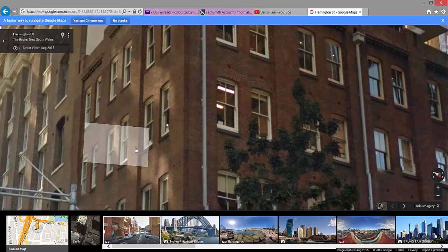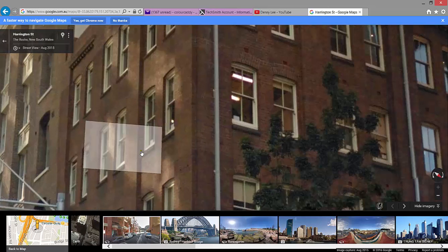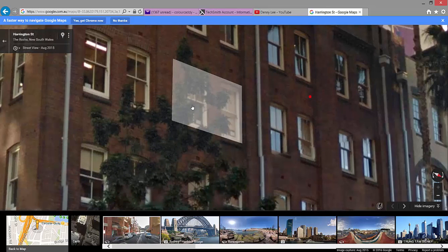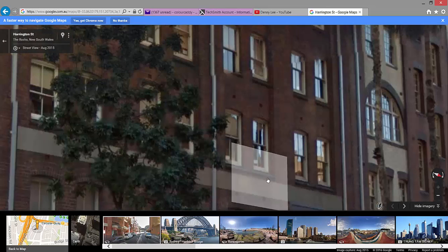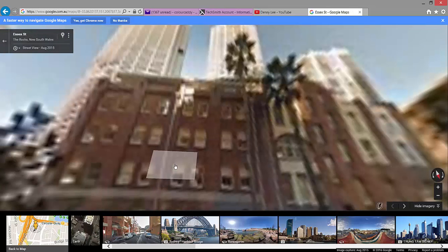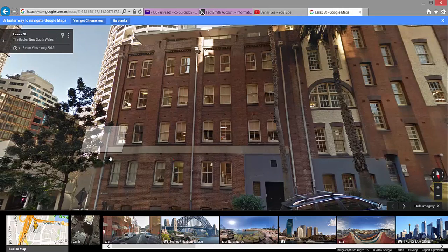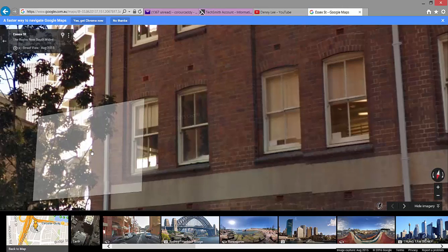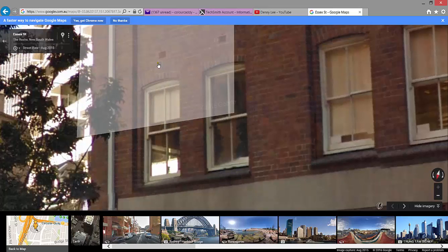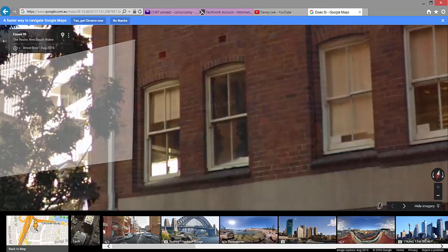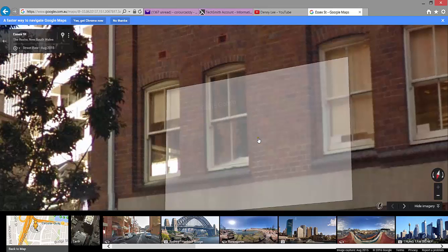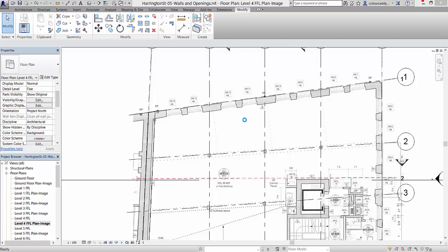Okay, so you can see there that essentially you have piers with the walls. If we zoom in, obviously being not as thick as the others, it's very difficult to see how many bricks even from the photo here. We can get a better angle. I think it's still going to be difficult. Oh yeah, that's not too bad. So we're looking at more than a brick thickness, but not much more. So let's just make it a nice round number and say 150.